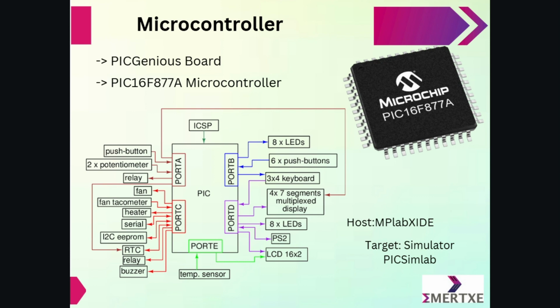Coming to the microcontroller, in this project we have used the PIC Genius board, which consists of the PIC16F877A microcontroller. This microcontroller has 4 ports. We use port B and D for the LEDs especially. Let us see in detail about them.